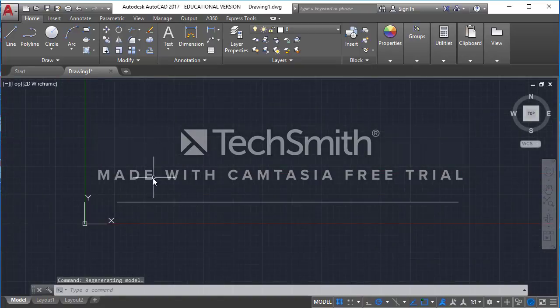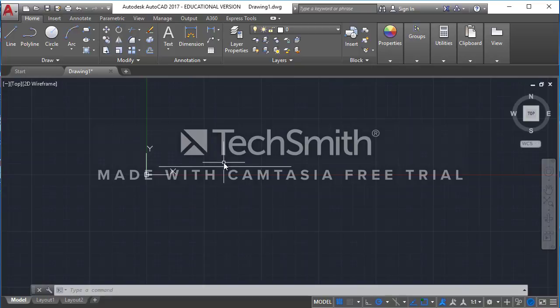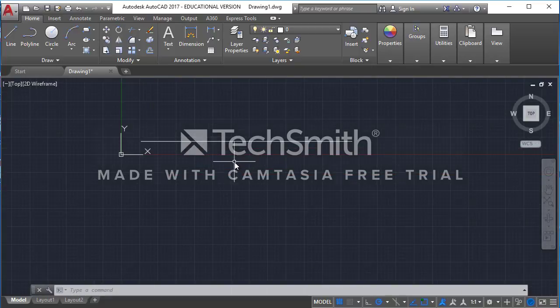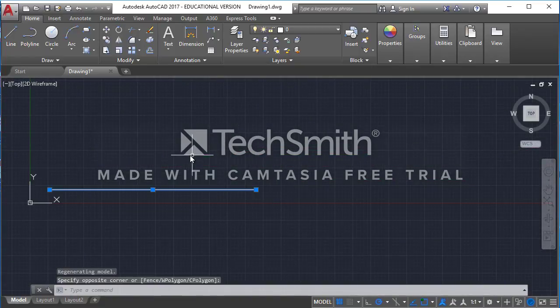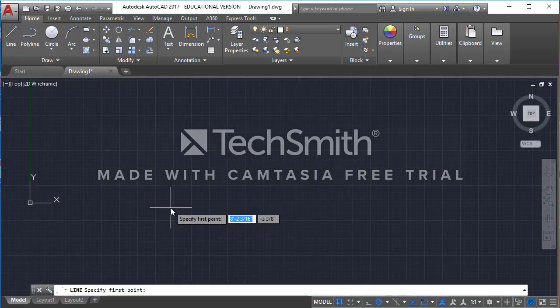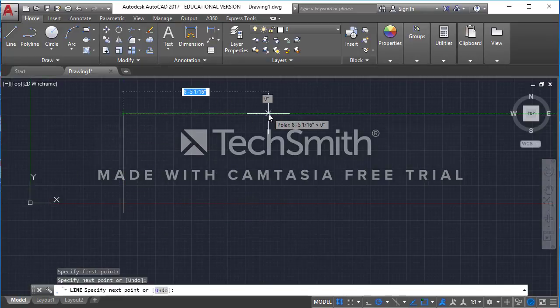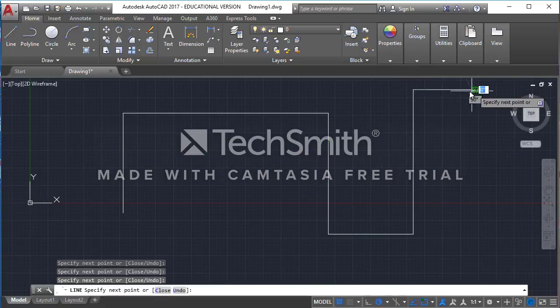A weird thing is that when you're in the middle of using a tool, it doesn't allow you to have the full extents of your zooming. But as soon as you hit escape on your keyboard, it will allow you to zoom in and out on your line. So that's going to be your basic line tool. You can click on the line button up here in your ribbon, or you can type in line or L for short, which is our shortcut, and you will be able to draw any of the shapes that you want.